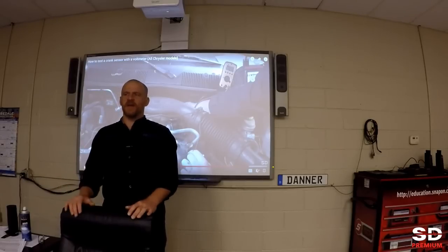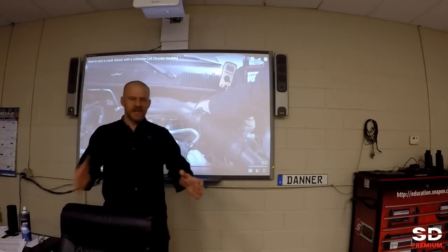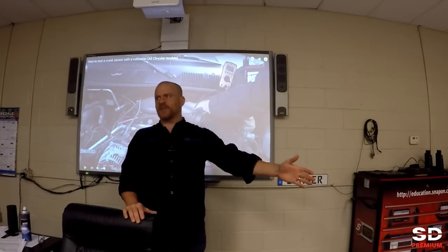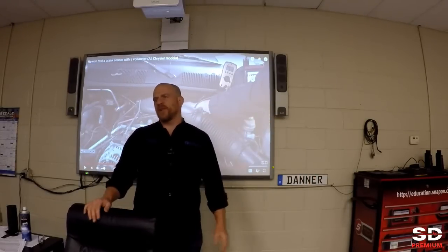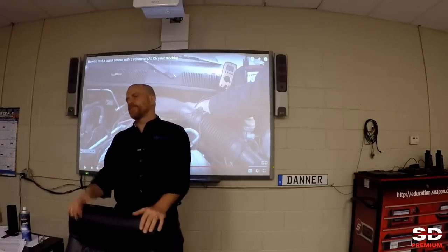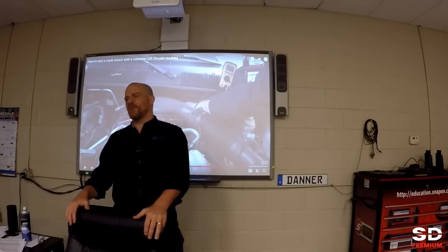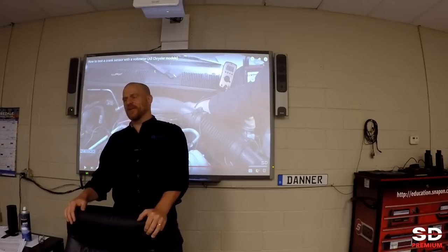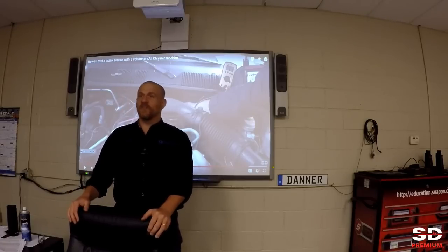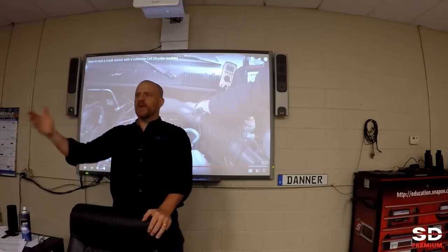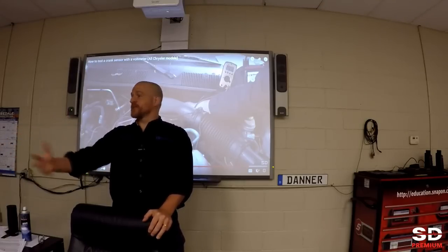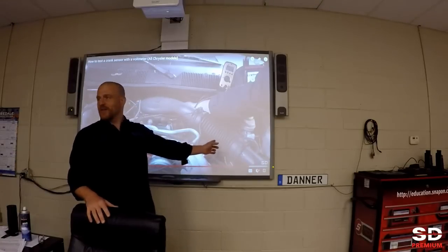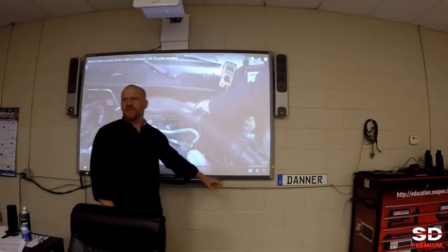Do you see where the bypass test comes in now? I take my test light, click, click, click, done, circuit's good, didn't have that reaction before. I'm 100% confident now I'm going to put a sensor in that. You can do this with any pull down? Yep. Any pull down circuit, on any year, on any make, and on any model car. And the only problem though would be, what reaction will you get? And are there variables? And I described the variable to you guys inadvertently, thinking that's where we were going with this. I don't think I even show the scan tool data on this.